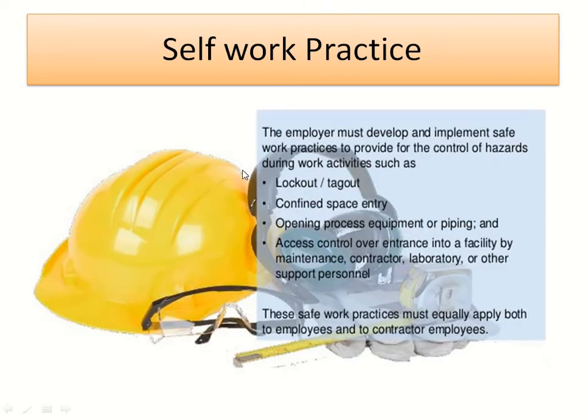Safe work practices. The employer must develop and implement safe work practices to provide for control of hazards during work activities such as lockout and tagout, confined space entry, and opening process equipment or piping.